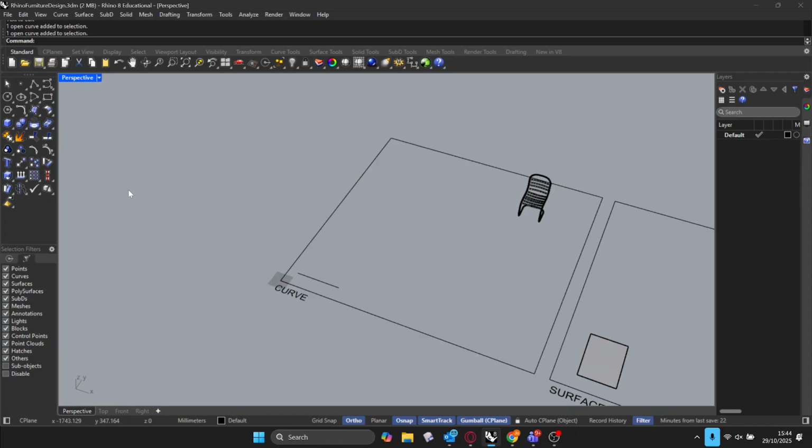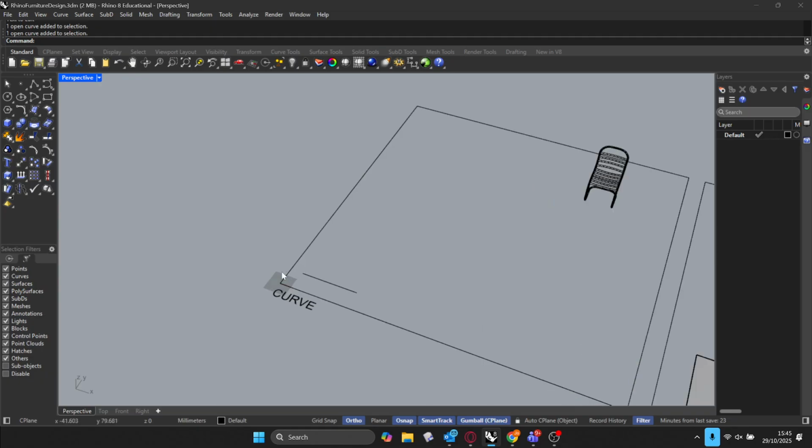So everything that we do is in relation to human scale. Whenever I'm choosing which file template to use in Rhino, I'll often consider what is the human scale that I'm working at. So if I'm working at a furniture scale, often I will work in millimeters because that's the nominal dimension that's used. If I'm working on an urban plan, I'll often use meters because in terms of the human scale, we've just scaled up. So I want to work with a higher scale. Okay, so I'll work with small objects, millimeters is what I'm going to be working with.